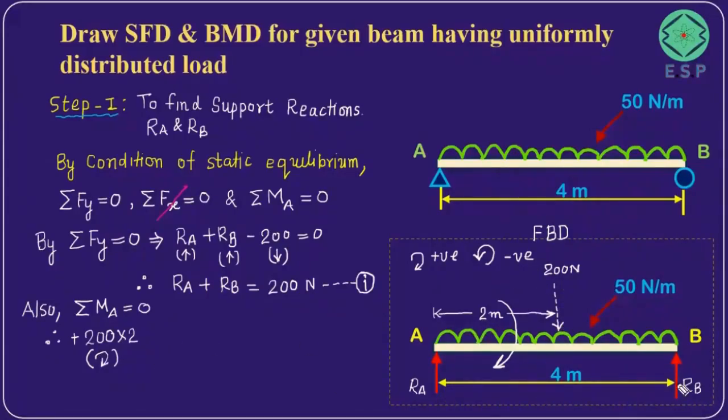Now the remaining force is RB, which is acting at point B at distance 4 meter from point A. So we can say that this force will rotate the beam in the anti-clockwise direction, something like this. So it will be RB into 4 meter but negative. So minus RB times 4 meters, and as you know that this is anti-clockwise rotation, this is going to be negative, friends, and that whole ends up equal to 0.